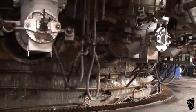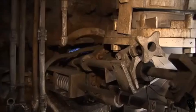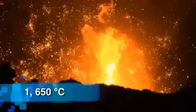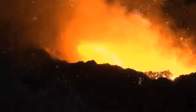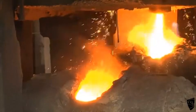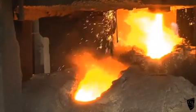Hot air is introduced under pressure into the bottom of the furnace, blasting the coke and smelting the iron ore in an environment of up to 1,650 degrees Celsius. In the lower part of the furnace, a graphite hearth or crucible receives the molten metal, which then is drained through tap holes and troughs and emptied into 200 metric ton capacity torpedo cars.